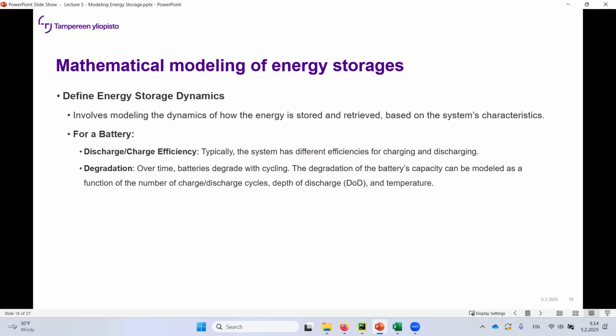When you do the cycles, it's going to start to degrade over time. And that's a matter of operational strategies. Are you going to use from 0 to 100? Because for a phone, for example, you might not want to charge it all the way up to 100 and use it till 1% and do that again. You want a bit shallower depth of discharge and charge.